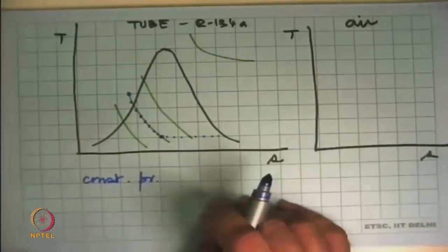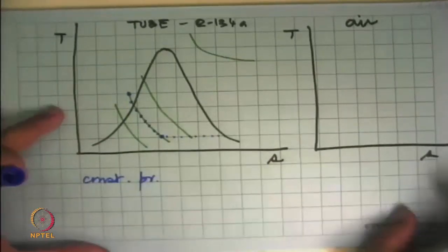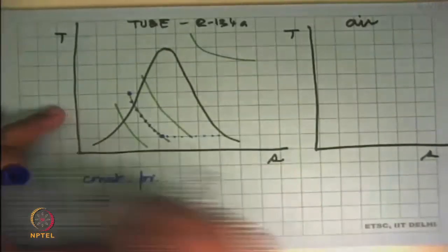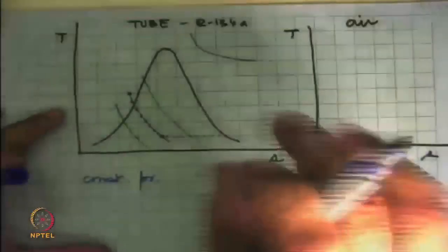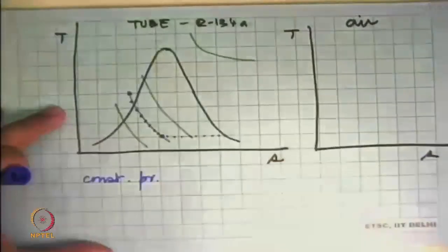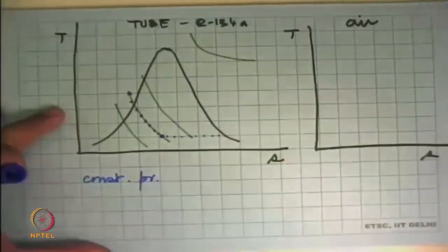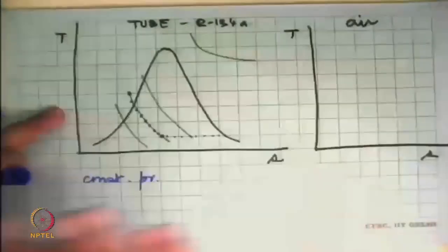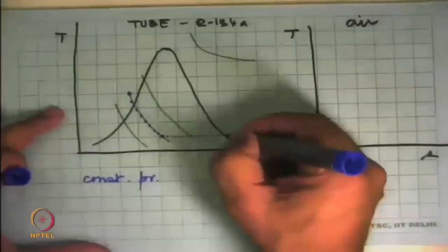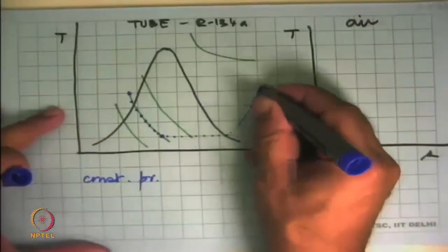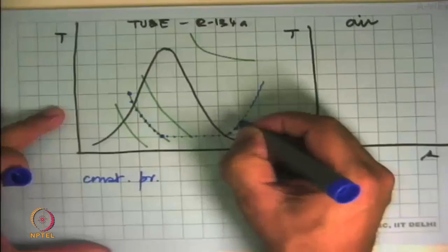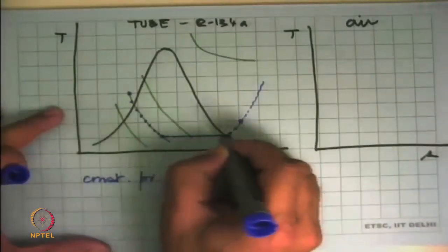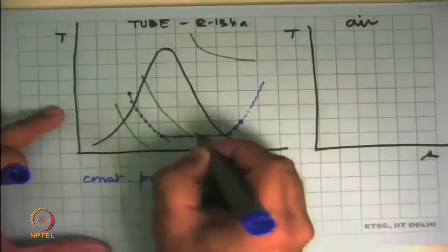We cannot have phase change with increasing pressure or decreasing pressure. And in all heat transfer devices, this fluid that goes through the tube, we are not doing any pumping on it. So the best and the easiest assumption is that the process, either on the shell side or on the tube side, is a constant pressure process. So in this case, it will follow the constant pressure line which is there. So it will follow this and end up over there. So the process that happens in that evaporator is like this.